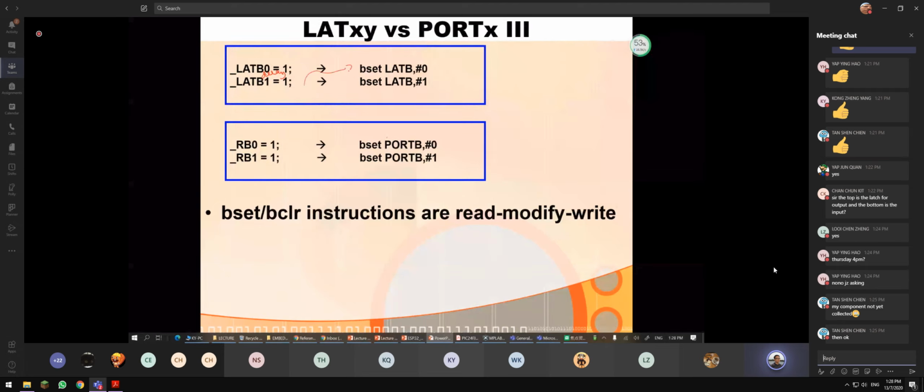Once you convert into an assembly program, there's a lot of things that will give you a delay. If your code is optimized and your microcontroller speed is super high, like 64 megahertz, then the datasheet advises you not to do something like this, because it might miss this. It is too fast, and you might miss this. Just to share with you only. But in your situation, it's not a problem.